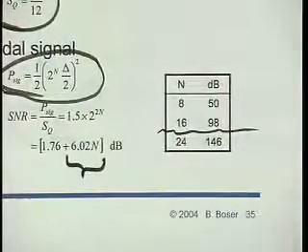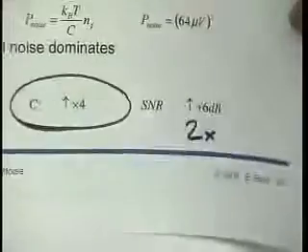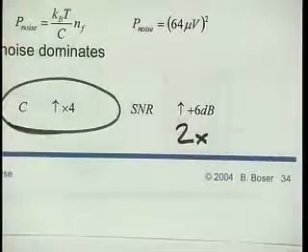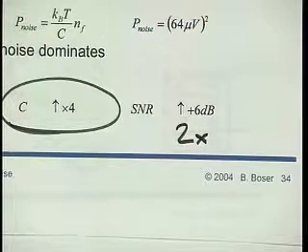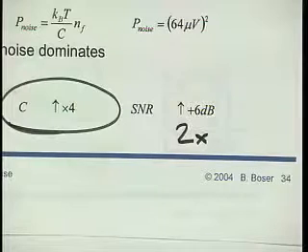Okay, so that makes sense now. That's why this example from before. An additional 6 dB of signal-to-noise ratio means that I improve my equivalent signal-to-noise ratio by 1 bit. So if I have a circuit that produces noise-limited accuracy to, let's say, 15 bits, and I really want 16 bits, maybe I have to do other things, but one thing I'm going to have to do is increase my capacitor by 4x.